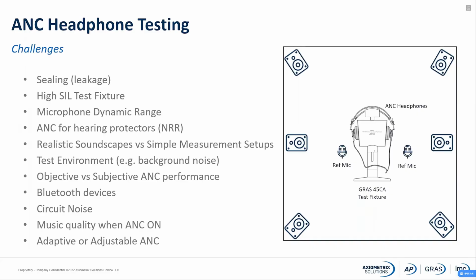One of the most popular parameters is loudness, or Zwicker loudness. There's an ISO standard about it. Loudness is basically the subjective perception of sound pressure level. So it's how we humans perceive sound pressure level. It's a sound pressure level measurement that considers the equal loudness curves of the human hearing model.